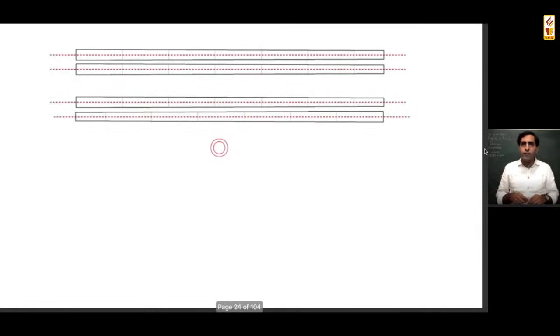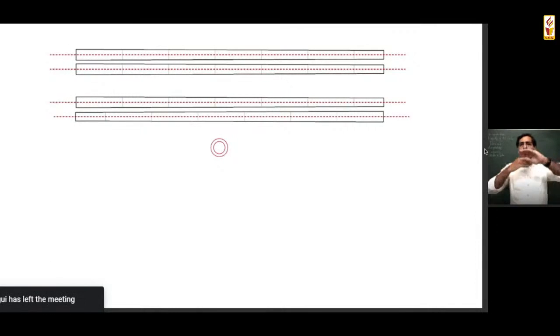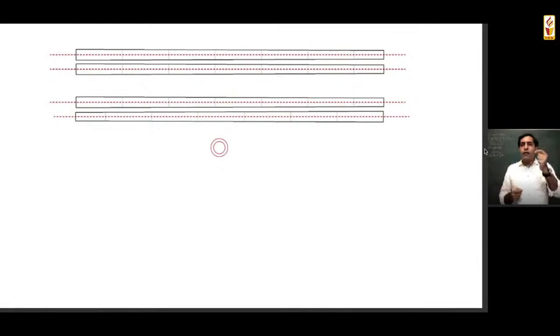Go next. So now I have placed 2 bamboos side by side, and the second one I have reversed. If you look, because there is a diameter variation, on the bottom and on the top the gap is different, which means that when you are detailing, you will have to take this into cognizance, because you will be seeing gaps. If you are not used to seeing a gap, there are ways in which you have to do it, which I will talk about later. But the point is, you should know that in the detailing, the tolerances have to be built in.